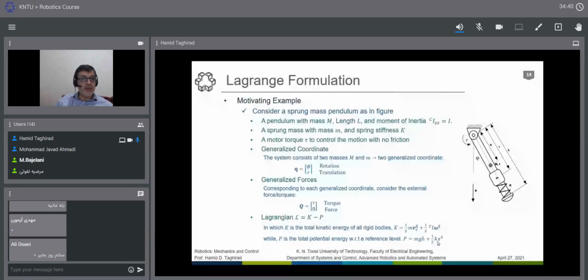For the robotic manipulator, we don't consider the stiffness, and if, as you see, there are some harmonic drives and something inside the system, then this could be considered as the elastic, as the kinetic energy there. So by this means we have the kinetic energy and potential energy. We just subtract these two from each other and we find L.